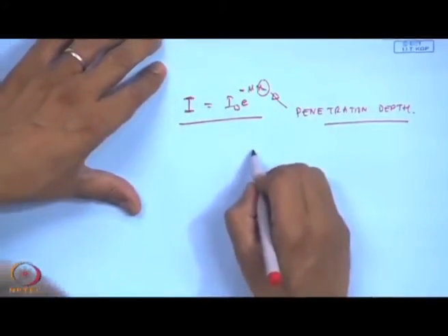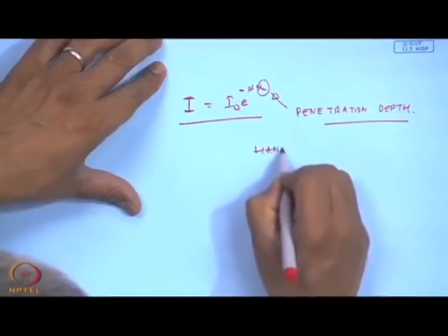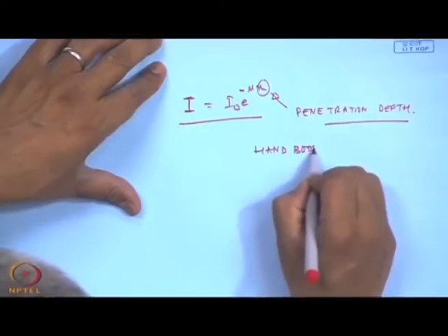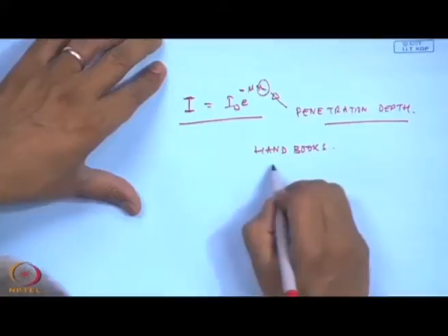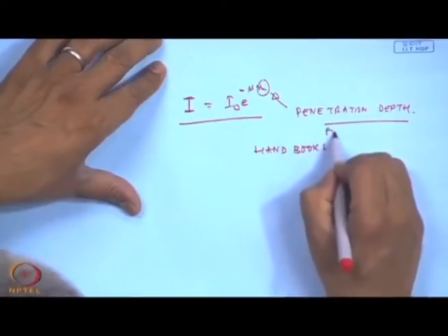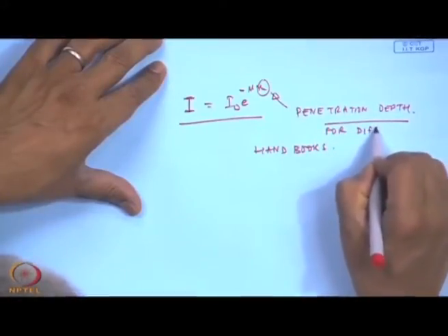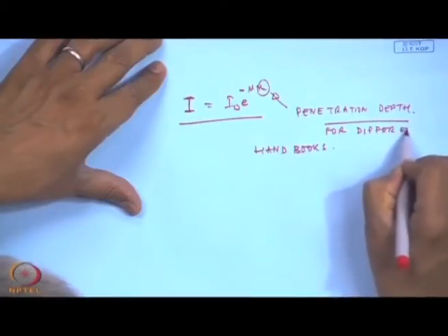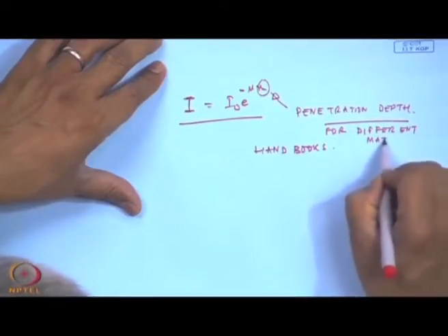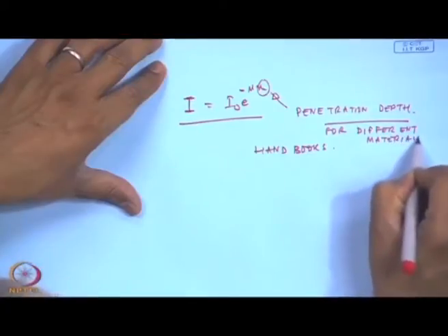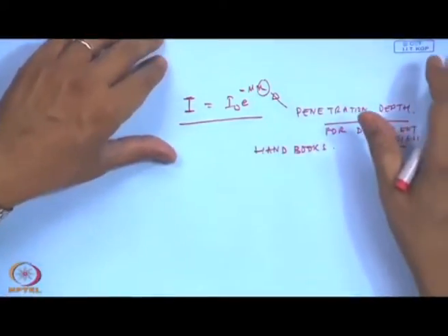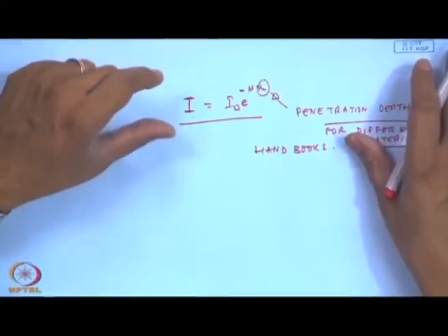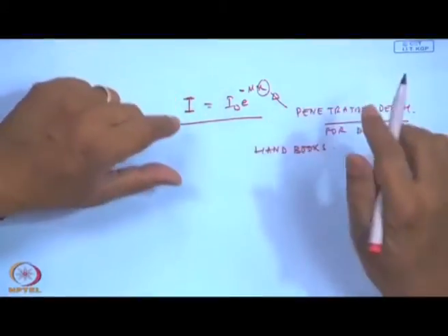So, these penetration depths for different materials are available in handbooks. And usually out of experience, the operators know that if I have a component surrounded by a material of a particular thickness, then the X-rays are appropriately absorbed, and nothing is going to go wrong.